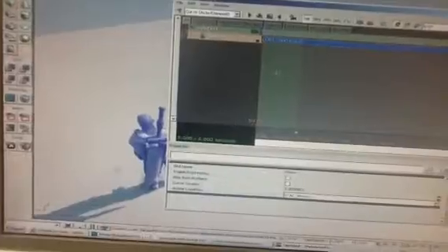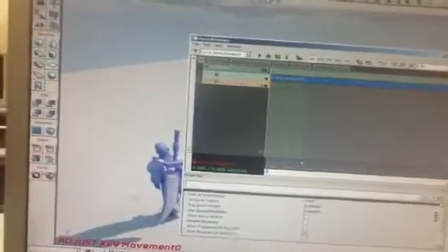The only problem is he's walking on the spot. So what we need to do is animate him slightly further so that he actually walks along, to make it a bit more realistic. So we're going to add a new movement track. Right click, under the movement track, you can scrub through the animation, so make sure that the bar is set to 0. Press enter to put a new movement key. That basically just tells us where his position is going to be when the animation starts.